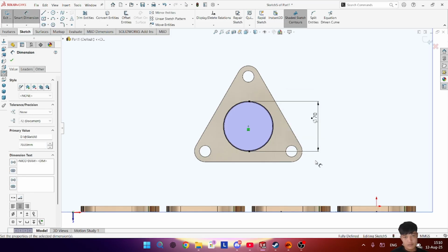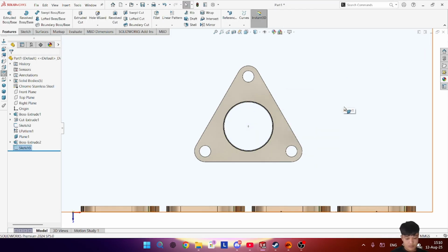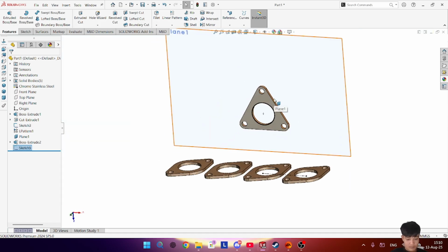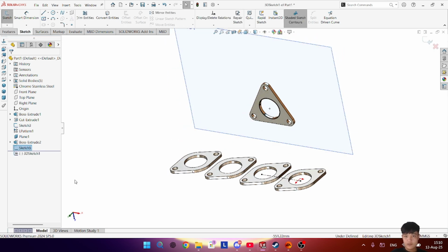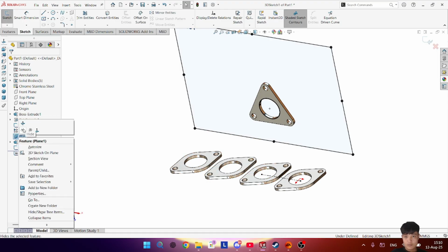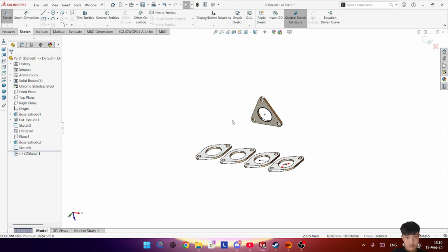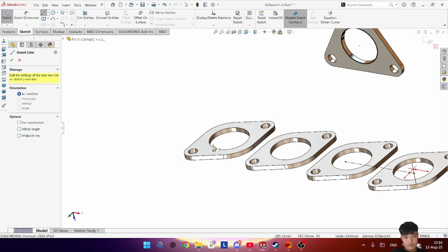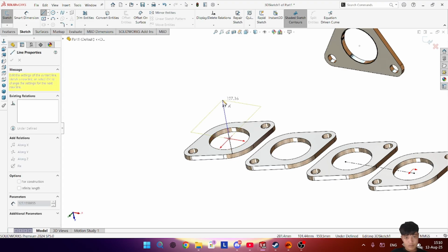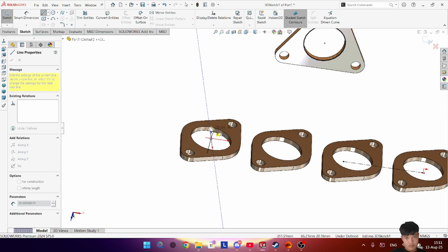Now let's go to 3D sketch. Now select this face and select line. If you go here, you will see a origin point. Exit. Again, choose the line, 3D sketch, and then let me select this circle. Not select, just keep your cursor and you'll find a origin point. Now you will see that arrow direction it goes downward. Exit. Now connect line again and connect these two points.